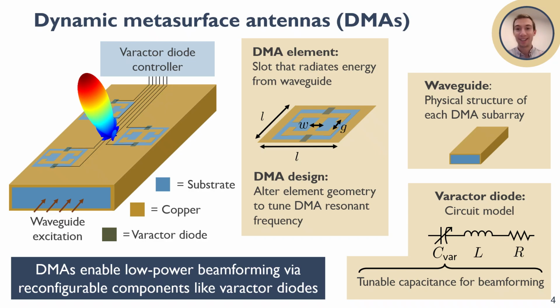So then what are dynamic metasurface antennas? These dynamic metasurface antennas are a sort of low power, reconfigurable slotted waveguide antenna array. So we have these slots etched out on a waveguide here with different varactor diodes or other reconfigurable components etched onto the top of them, and we can control these with an external controller. And as we tune these varactor diodes, we can actually enable beamforming.